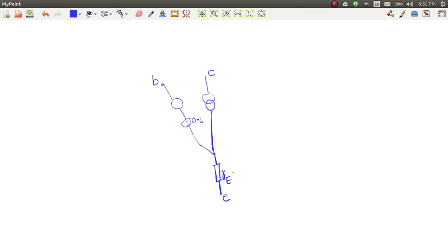And just to remind you, RE is VT, the thermal voltage, as a function of temperature. That's why we write VT divided by the current that we have. We call it IC. It's a collector current, but it's the current of the circuit. So VT is KT by Q, and it's not necessary to remember it's KT by Q, except that it's proportional to temperature.